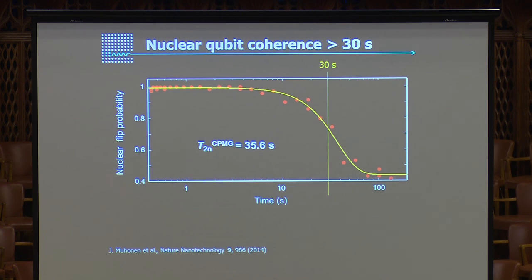If you do it on the nuclear spin, you have two options. You can use the nuclear spin when the electron is on the donor. You can remove the electron and just manipulate the nuclear spin alone and bring back the electron just to read it out. The coherence gets a bit better that way. And so this constitutes, as far as I know, the longest single qubit coherence in the solid state ever measured. It's 35.6 seconds. This is in a silicon MOS nanoelectronic device, okay? I want you to ponder on that. It's half a minute coherence in an essentially modified silicon MOSFET, okay?